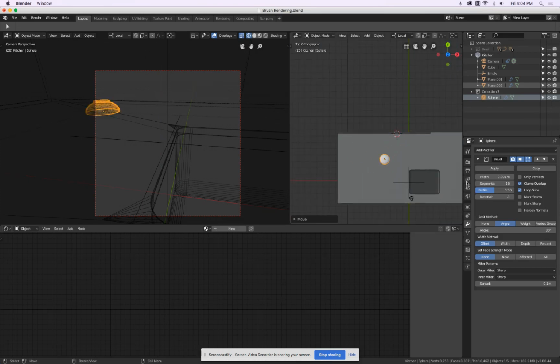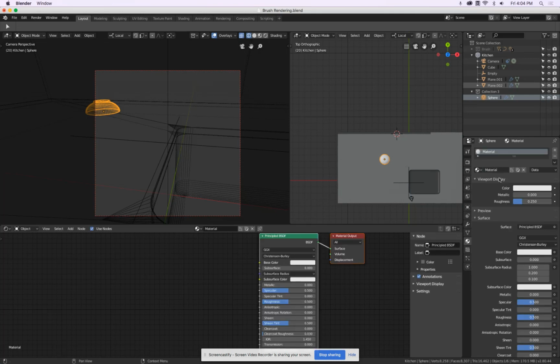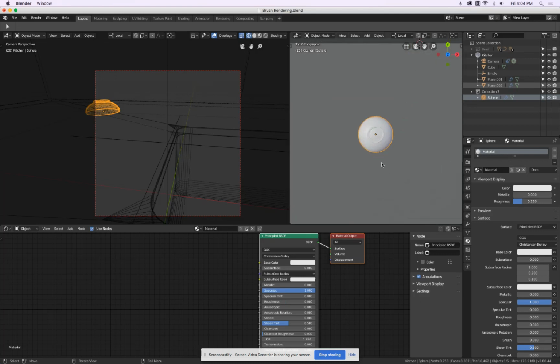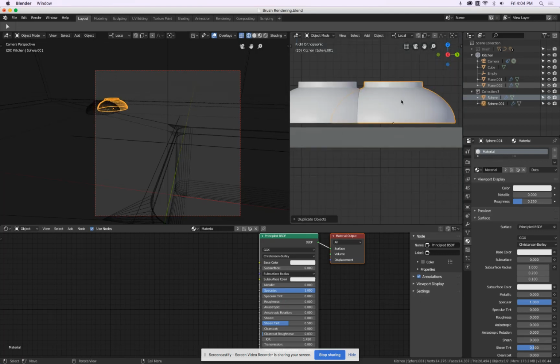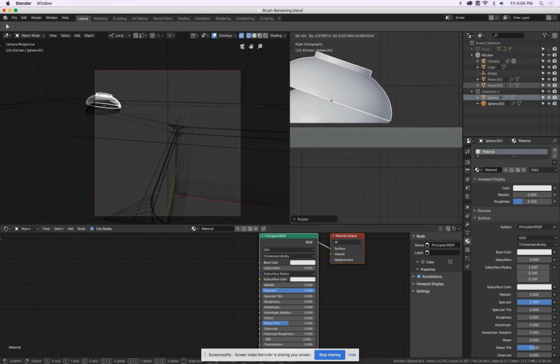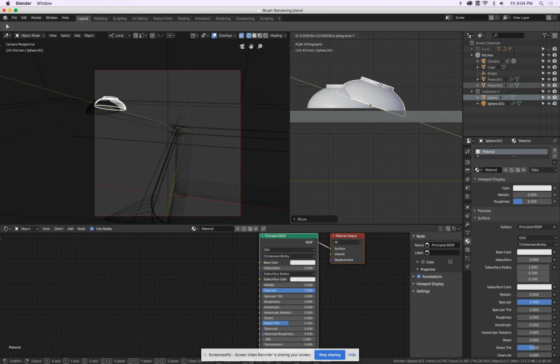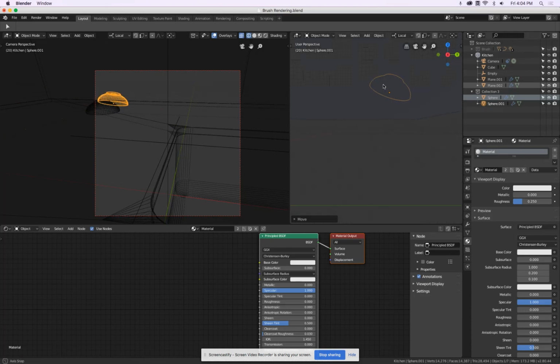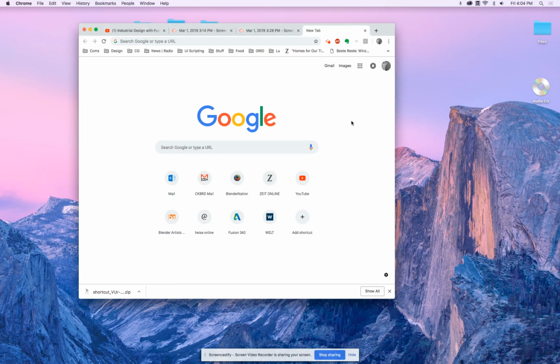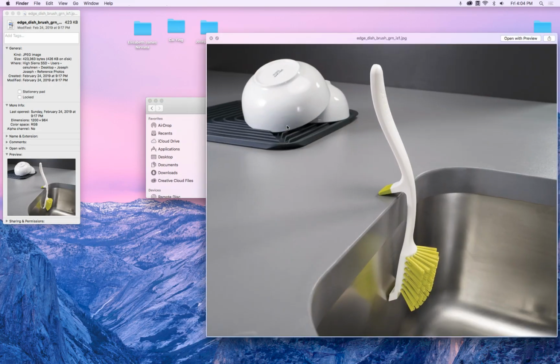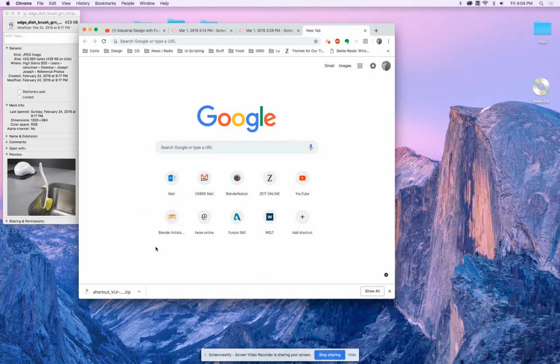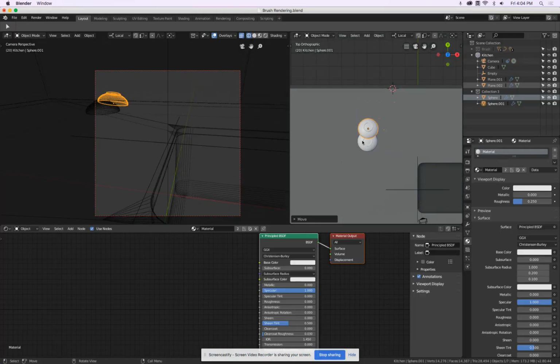And to there. That should be, let's say, porcelain. Just kind of high glossy, not really rough. Shift D, make a copy, move it to there from a side view. We're rotating this. There, G and Y, and Y. Say like this, okay. And we know this is on some sort of a drying rack. Just make a simple block this sits on.